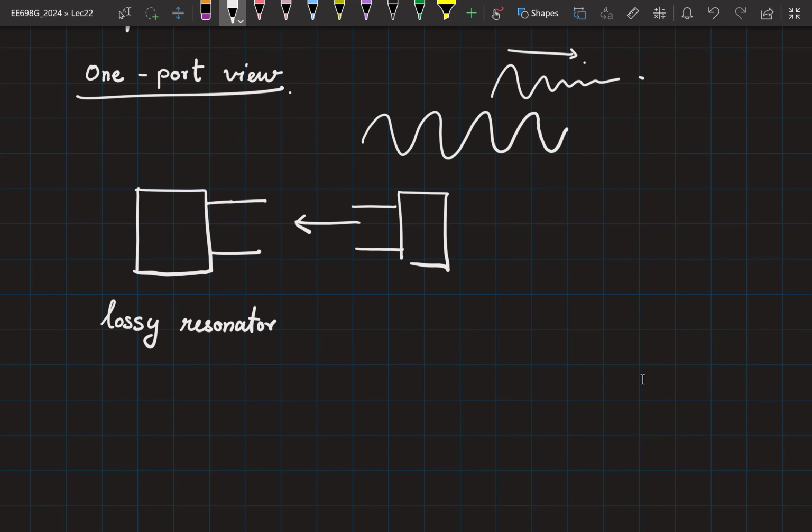So the same method, every cycle some energy is lost from the resonator. I will connect another component here that is able to replenish that energy in every cycle. So if the lossy element was some resistance Rp, I have to connect minus Rp here. Of course, you don't get negative resistances directly. You will have to use active implementation to realize a negative resistance, right?